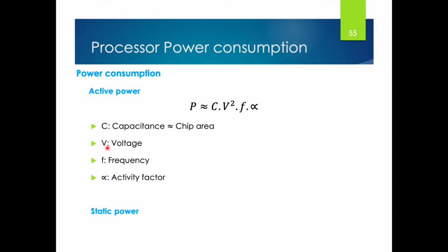In particular, voltage may significantly increase dynamic switching power, because you can see here in the formula, active power is directly proportional to the square of V. So if we increase V by a small amount, the power consumption will increase significantly. Conversely, reducing the voltage may cause performance reduction, but at a certain point, reducing the voltage may prevent the design from operating properly.